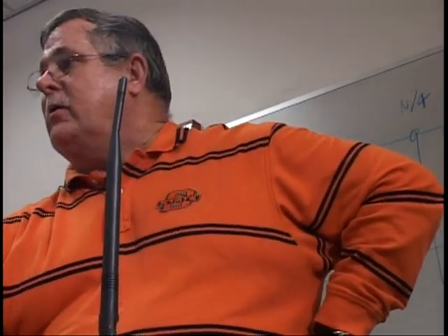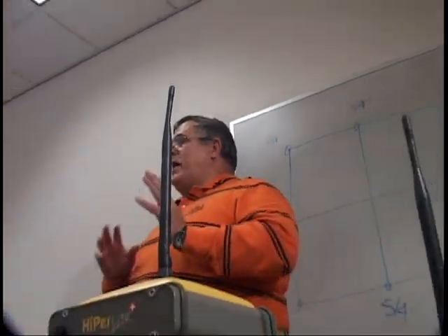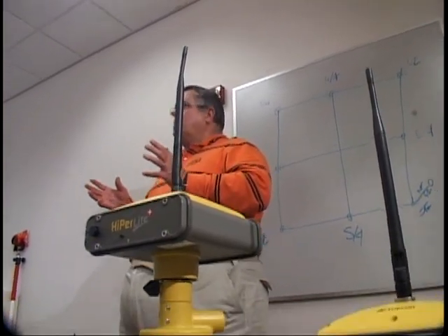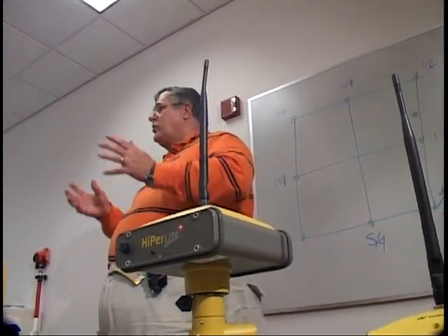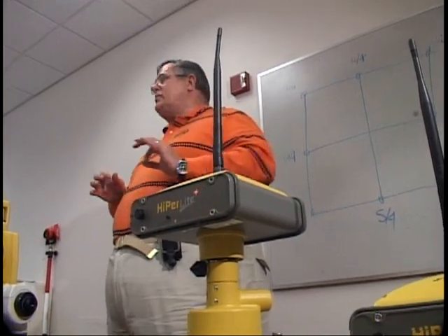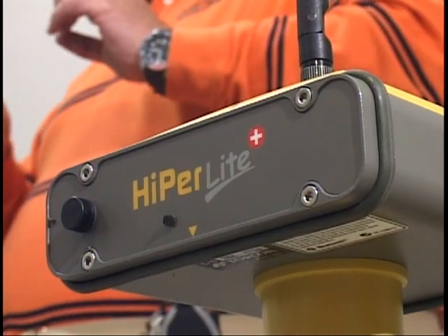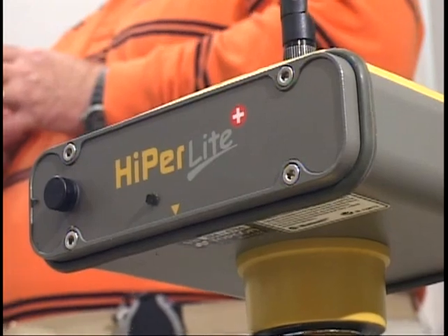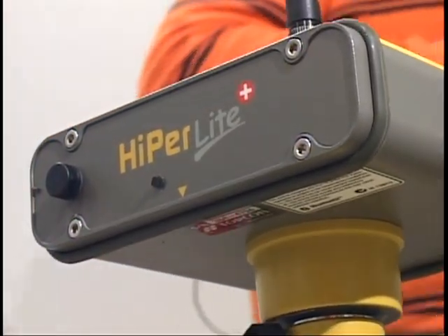When you use either a total station surveying instrument like this or use a transit with your field notes, you can run around that property and see how it closes. And very often, or sometimes I should say, you find that there's obviously been an error made. You can track down those errors. When you're using GPS and you only take one sighting, you're not exercising the ability to check yourself. Surveying instruments are only going to get more and more sophisticated.